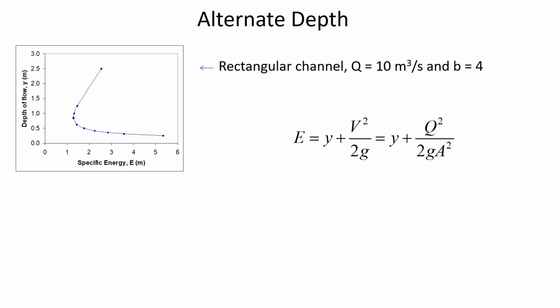And it's the slope of the channel that determines what the depth is. So there could be a really steep slope where there's a fast-moving water velocity, and most of the energy exists in the form of kinetic energy. Or it could be a shallow slope where the water has to be pretty deep, and most of the specific energy exists as the depth because there's very low velocity.